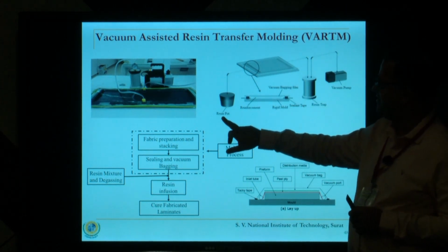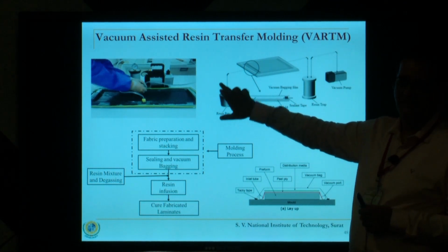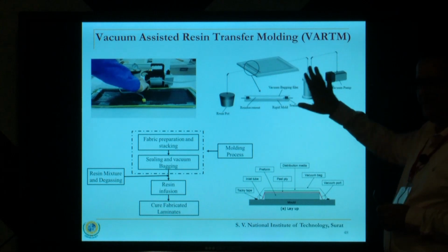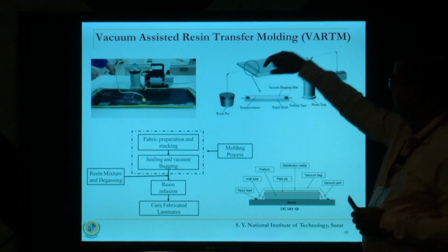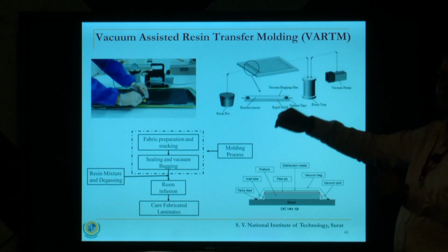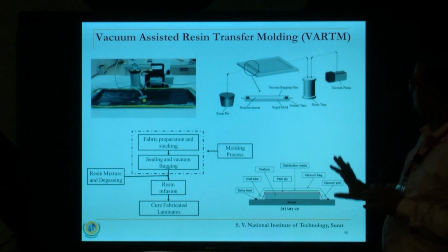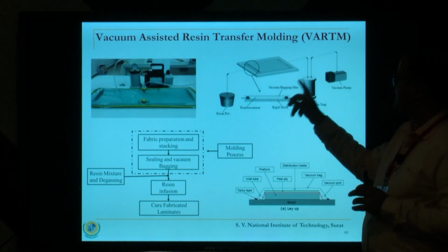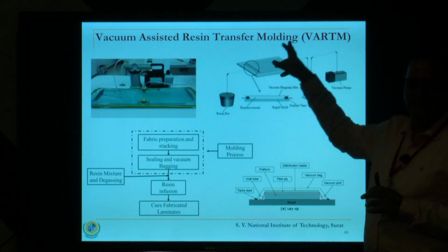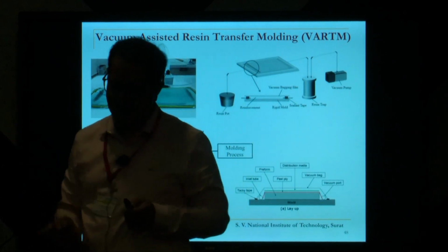And on the other side, I have a resin pot. So, here the prepared resin is placed and it flows from here into this. Once it comes into this part, then I will have to seal both the ends, so that no new material comes in, no material moves out, and that is sealed and that is put up for curing. So, these are the interesting things of this part. This is easier to make, but then managing this thing simultaneously is slightly, it is not difficult, but it is slightly tricky.